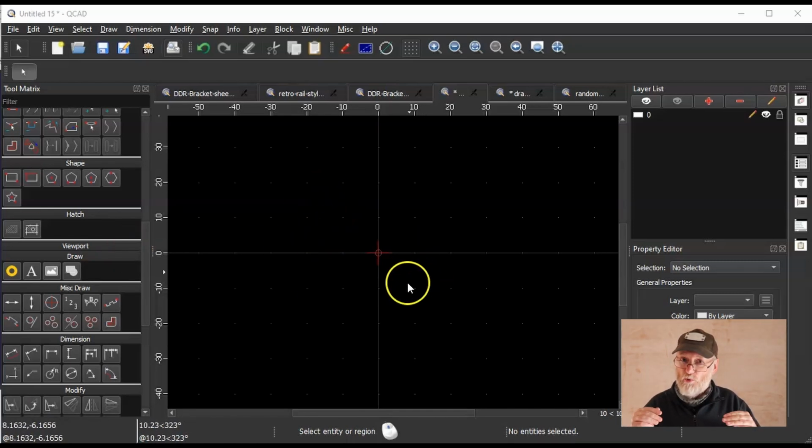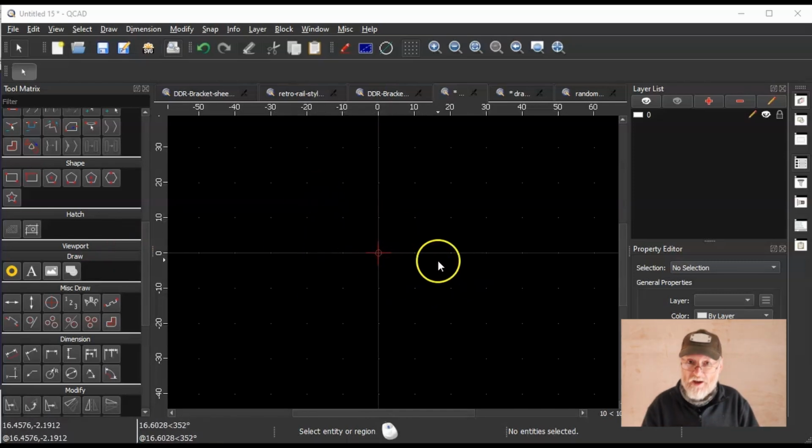And that brings us on to where to do your drawings within that plane once you start. It's tempting to just lay them down anywhere, and I see quite a lot of videos online where people are just drawing randomly in this infinite space. They might be near or close to the center, but they're still off somewhere. Every CAD package has a 0 point. It's normally some kind of crosshair in the center of the screen. That's where you should start all your drawings from, and you should keep it within that element and go out from there.